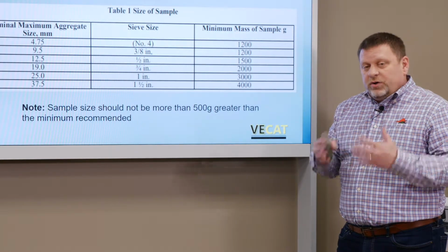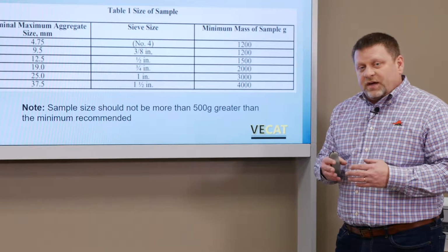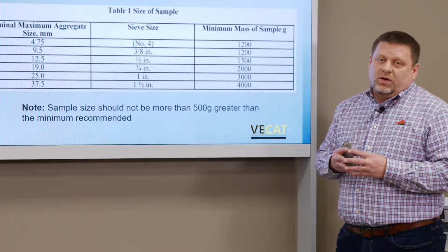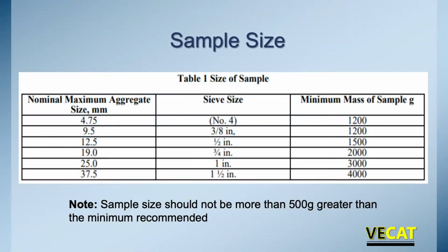And now, all the samples that you're doing your furnace correction factor with should be similar to the sample weight you're going to use when you're actually doing field production. Sample weight can impact these test results, so you want to keep that as constant as we can.